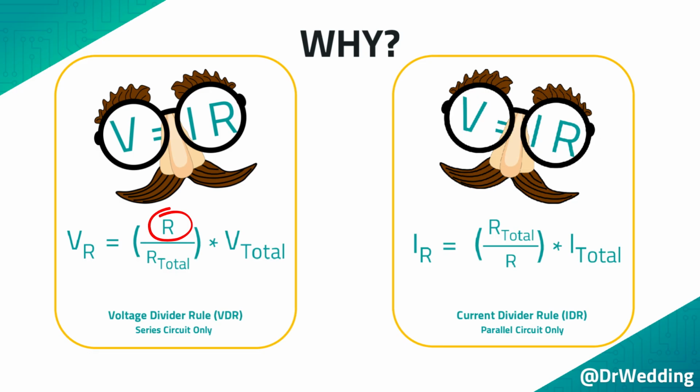In a series circuit, large resistors take the most voltage. In a parallel circuit, small resistors take the most current. Furthermore, these two equations can help in more complex circuits. However, at this point, it is difficult to demonstrate how these two equations are used because we have not covered series parallel circuits, Thevenin voltage, and Norton currents.